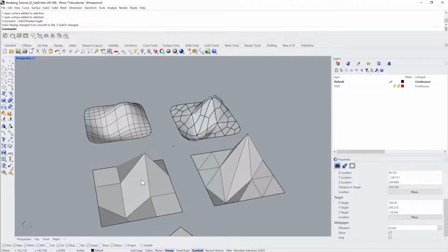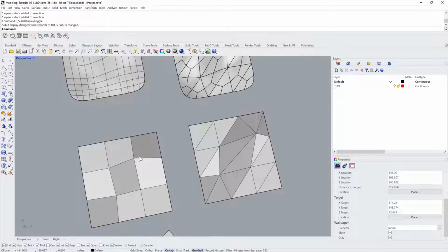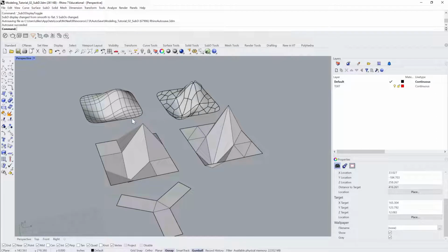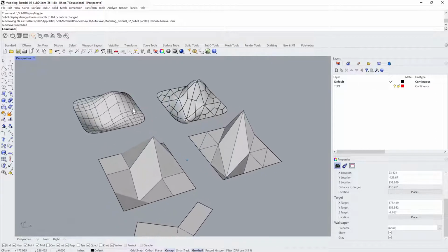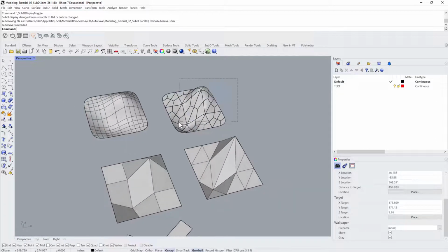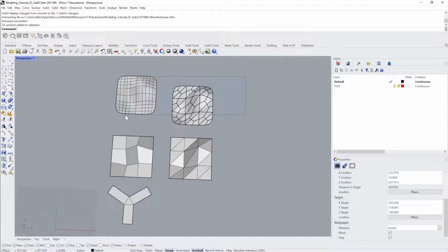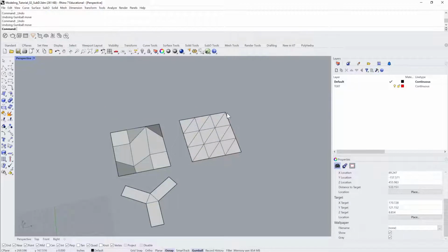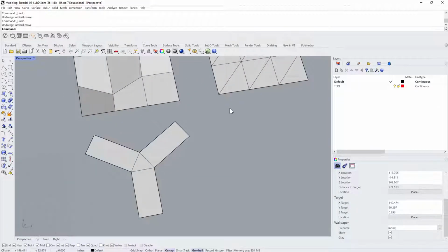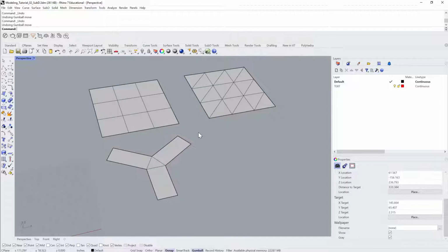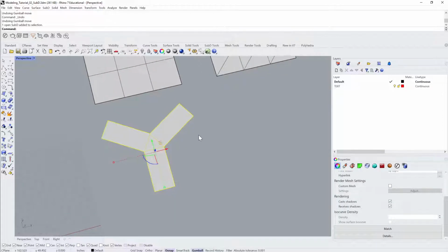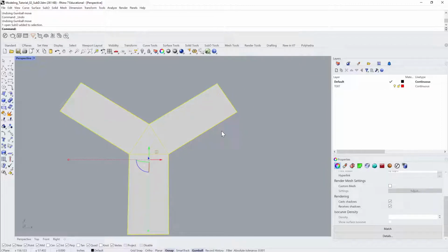And so this is just to say that you should try to maintain your geometry in the configuration of all quads as much as possible if your destination for the geometry is going to be a smooth surface model. All right, now there are, of course, some exceptions to every rule, and one of the exceptions will be this type of configuration, which is known as a Y-joint.